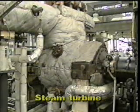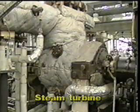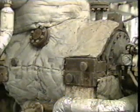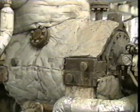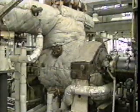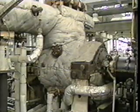In steam or combustion gas turbines, speed-increasing gears are often needed between the turbines and the compressor shaft and are connected with couplings. Commonly, steam and gas turbines use speed-increasing gears between the turbine and the compressor. Steam and gas turbines generally rotate at high speeds and therefore can sometimes be used to drive high-speed centrifugal compressors without any gearbox. This is known as direct drive.